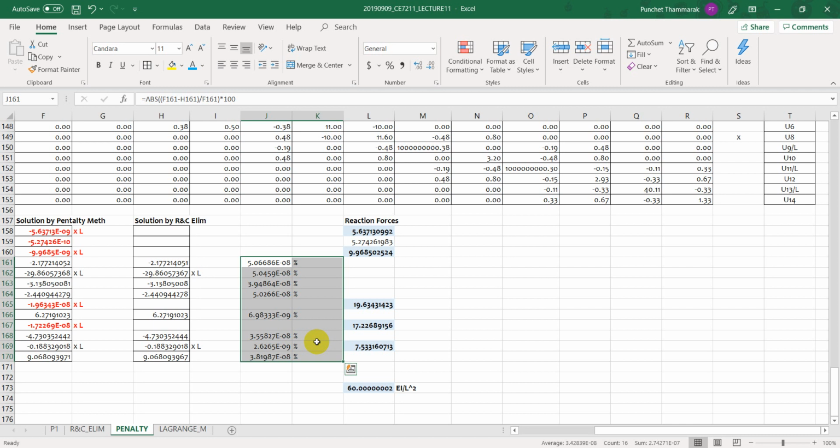So different mesh sizes are expected in some problems. In some areas where you don't need so much accuracy, you just use a big mesh. That difference could lead to the issue I mentioned about the ill-conditioned matrix.